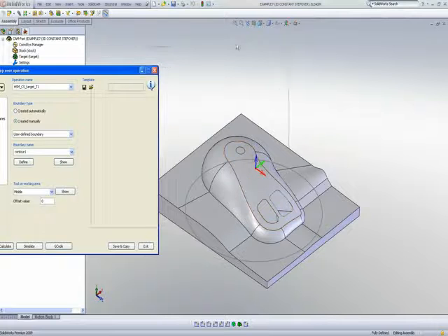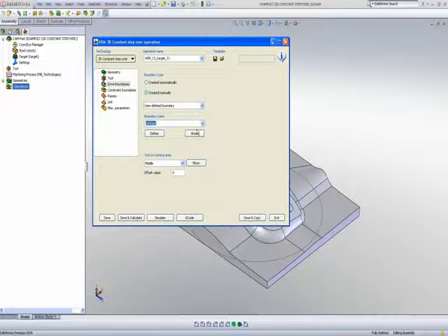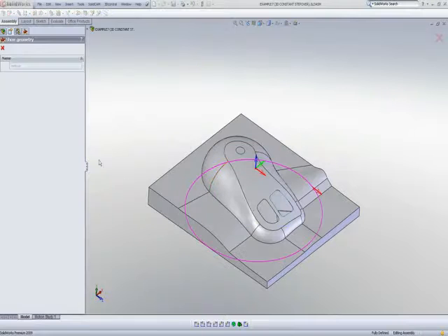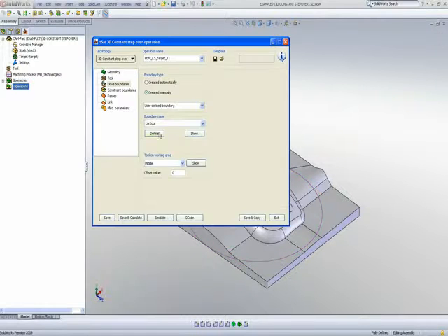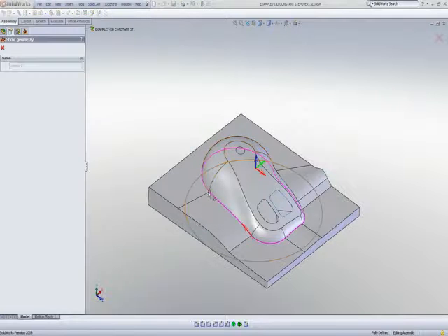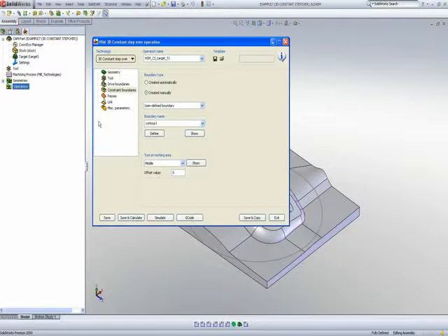Let's first start, and we'll use the option of using our circular tool path as shown over here. I'll use my working area as external, and for my constraint boundaries I'll use create manually, and in this particular case I'll use this area around the mouse itself to be my constraint boundaries. In other words, I'm going to have a circular tool path, but it will only go up until the edge of that mouse itself, and again I'll use the option of external.